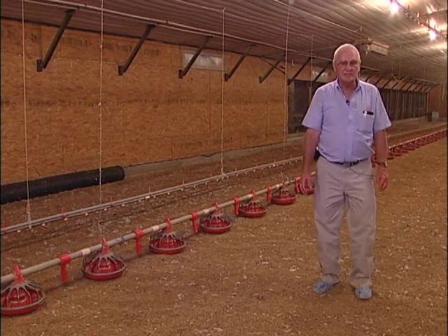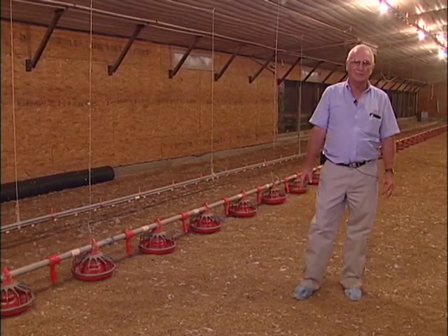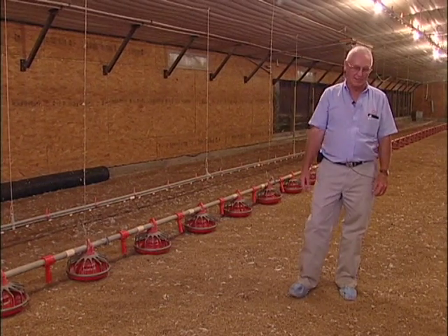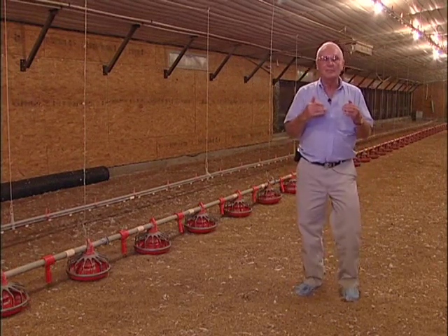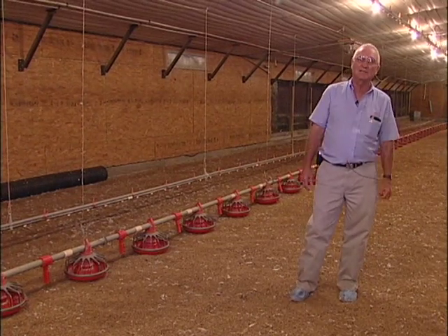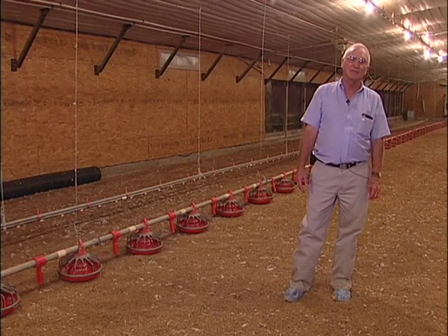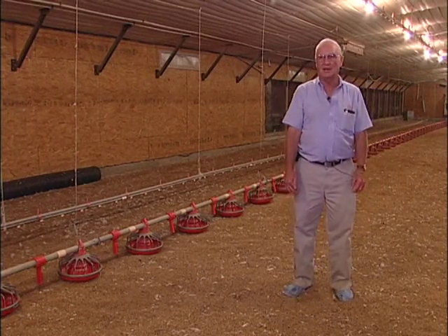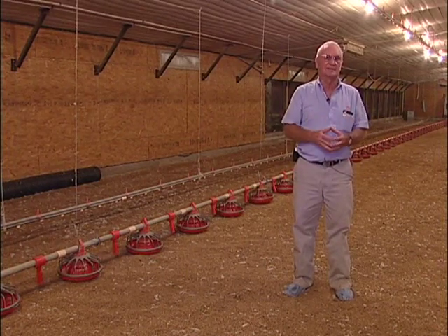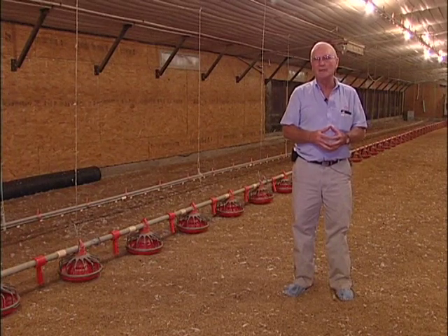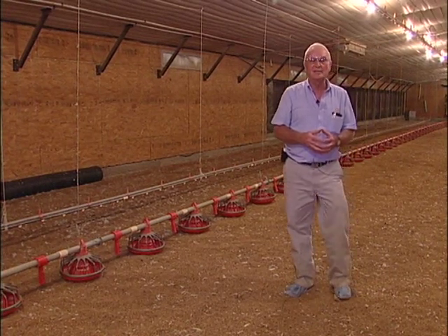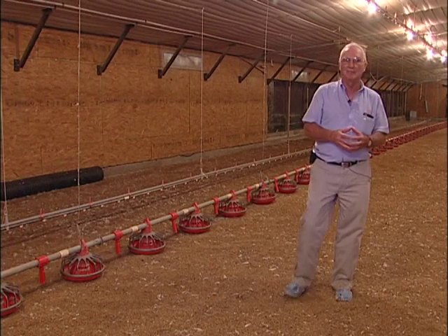All right, another thing I want to discuss is the question that always comes up: whether to run your pads, or your pumps on your pads, with less than all your fans running. Since the pad surface area is determined totally by your total fan capacity, you should never run the pumps on your pad unless all of your fans are in operation. For example, if you had your pad sized for 8 fans and the air through it was 400 feet a minute, and you only had 6 of those fans running, then the airspeed through the pads would be less than 200 feet a minute.